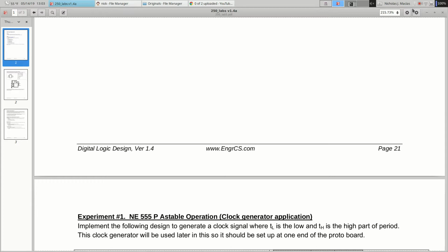But that picture of a fuse map, if there's 128 connections, would be a huge picture to draw, and there's no benefit to knowing that this particular output goes to the second input of this AND gate and so on. So we use that abbreviation when we see pictures of the fuse maps, because all we're doing is saying which fuses we blow, which lines are connected to which. But it's not a circuit diagram in the standard sense. Yeah, I can see that. Okay.